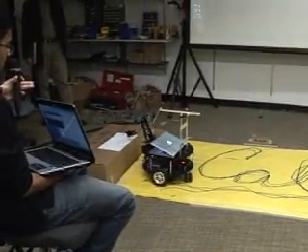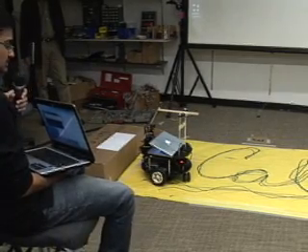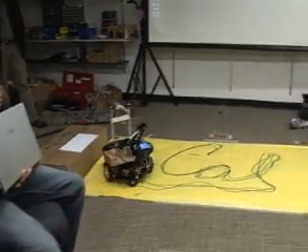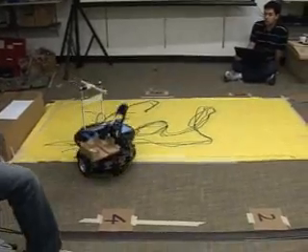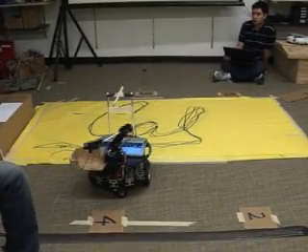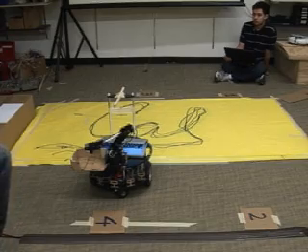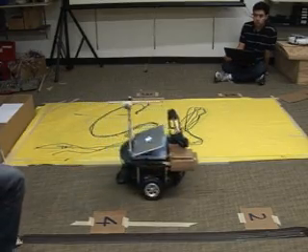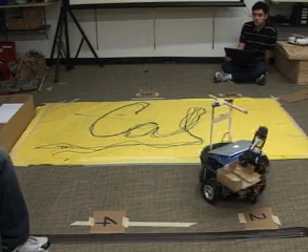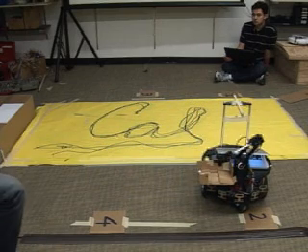And then after it does that, it'll start going to each of the tables. One of the invariants that we have in our path planning is that if a table makes a request, the robot will first go to the chef's table and then go to the table to service. In other words, it's not going to go to the table first and then go to the chef's table, since it would be pretty nonsensical to bring it nothing.